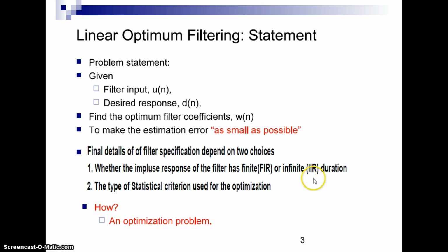The presence of feedback in an IIR filter means that a portion of the filter output, and possibly other internal variables in the filter, are fed back to the input. So unless the filter is properly designed, feedback can in turn make it unstable, with the result that the filter oscillates. This kind of operation is clearly unacceptable. So FIR filters generally provide stability, while IIR filters can be unstable. That's why most of the time we prefer FIR filters over IIR filters. That is one thing we have to observe.